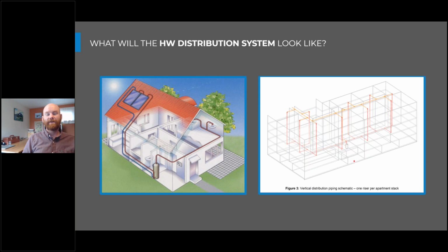So if we have this large distribution network, we're likely going to see higher temperature maintenance losses, which will have more of an impact on that single pass heat pump water heating equipment or our system overall. So the first thing that I always ask myself when I'm working on a new product or project is, what is this distribution system going to look like? And that's going to lead me to a few different design approaches to address that concern with the warm circulation water returning to our primary storage.